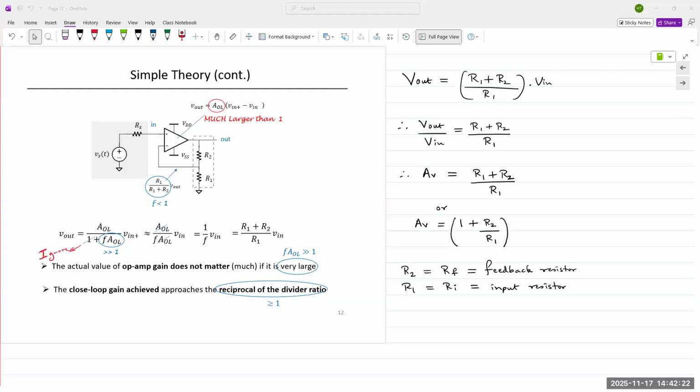So this is a very good question. This is not talking about the gain of an op amp. This is talking about the non-inverting amplifier created with an op amp. So it'd be two different things. There'll be op amp properties, ideal op amp properties, and then circuits we create with op amps and their properties. The gain property of this circuit would be 1 plus R2 over R1. If you didn't feed the output back into the input, it would be a completely different circuit.